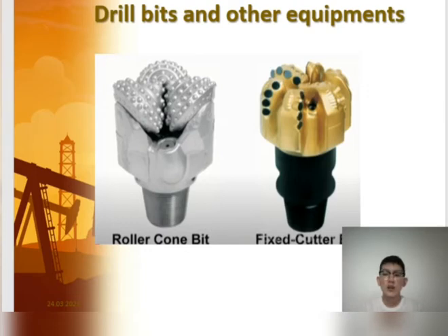After each casing we have to cement it, and the cementing will be outside of the casing. And the cementing has primary and secondary types. Primary cementing is carried out when our casing is run, and secondary cementing is carried out when remedial work is required.